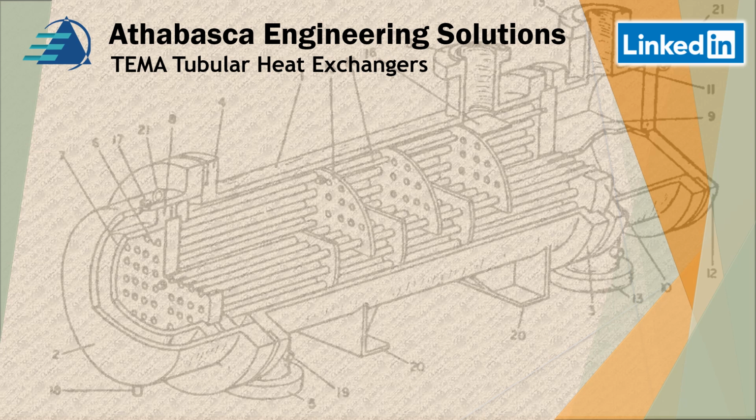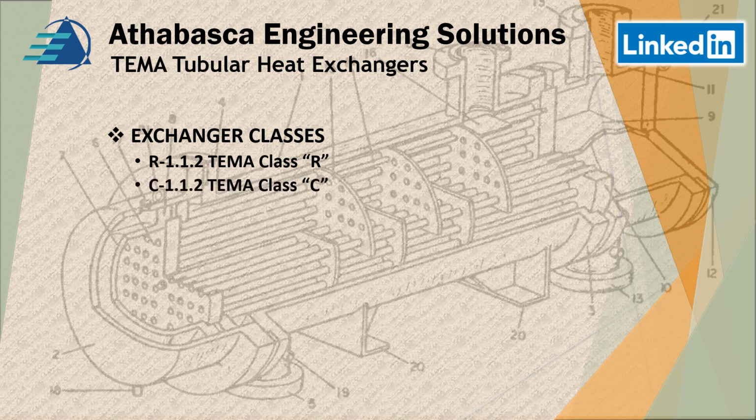TEMA exchangers are divided into 3 different classes or groups, and the construction will vary with the different levels. There's a type R, C, and B, which is shown here. TEMA Class R, which is R for refinery, and then C class and B. So in order of highest cost is R, and progressively lower down to B. But in terms of reliability, you trade cost for reliability. R is the most reliable of those components.